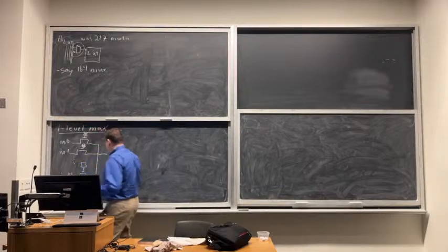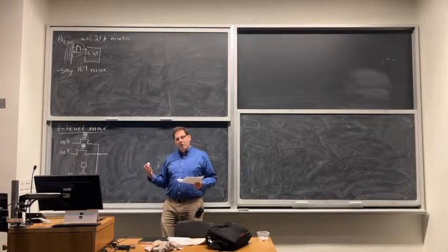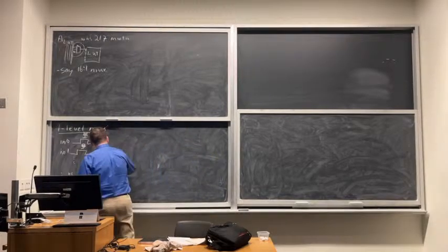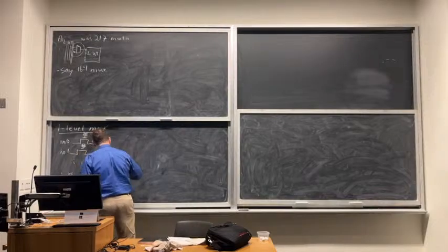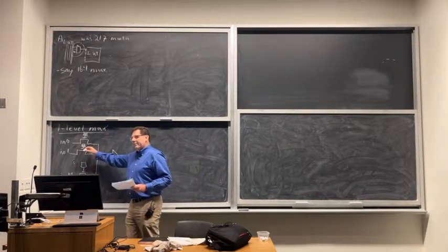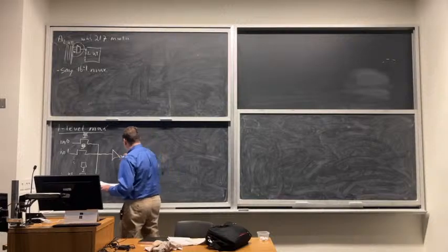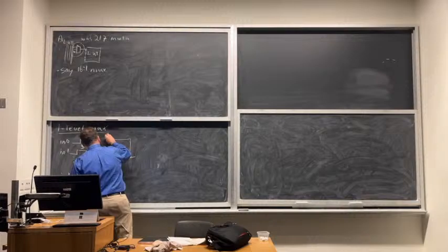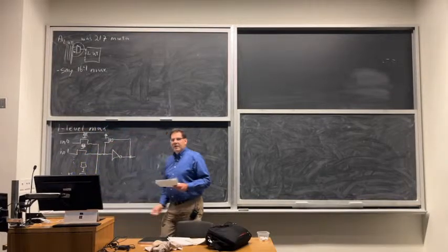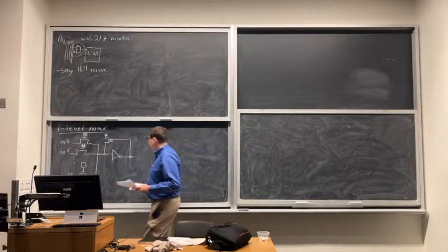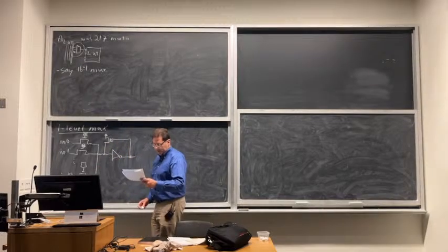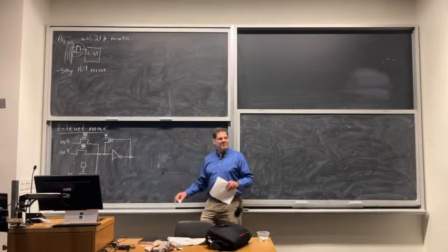Okay, they're pass gates. We already saw last week that pass gates don't transmit a logic 1 very well. They degrade it by a threshold voltage. So I should put an inverter on here anyway, because I don't want to put a big capacitive load on my pass gate. So I put an inverter to isolate it, and that's not quite enough. I also need to put in this little level restoring circuit where I put in a weak pull-up or a keeper transistor that makes sure that eventually this signal goes all the way to VDD, because otherwise it wouldn't, and this inverter would leak a lot. Is everybody with me on that one?